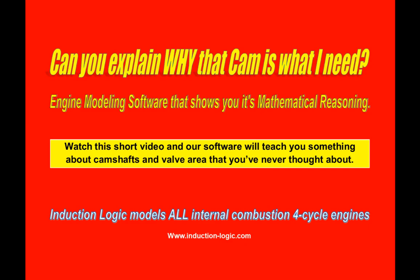Let's model that 750 horsepower, pump gas, street strip, small block Chevy. To make that much power, we're going to need cubic inches. So, we'll start with a 4.155 inch bore, a 4-inch stroke, and 6-inch rod. We'll enter 9 inches for the deck height, which gives us a 1-inch compression height.